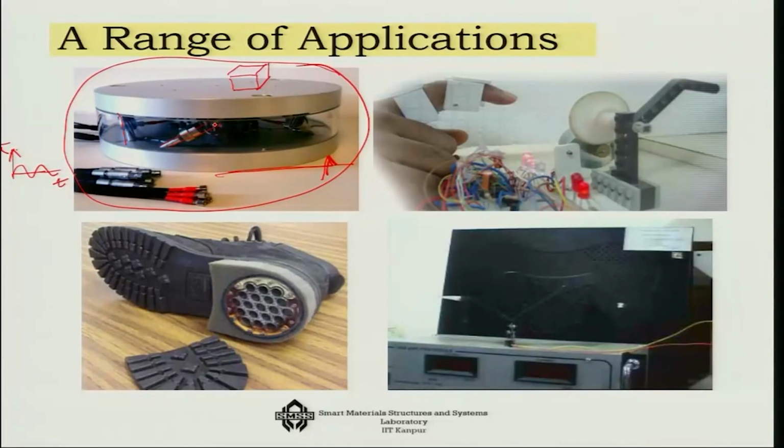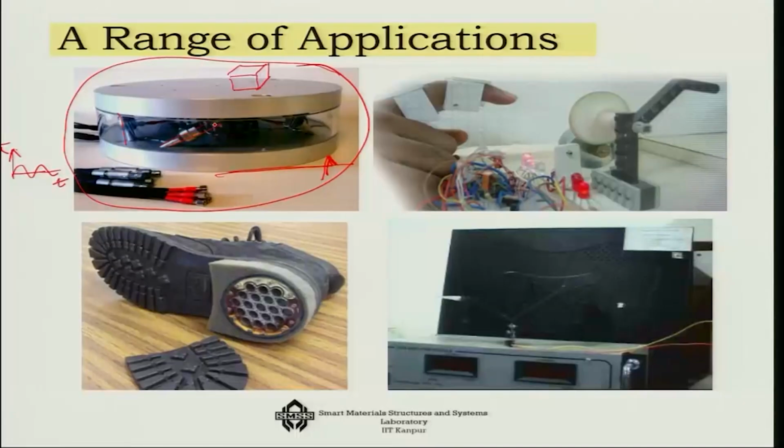That means the system is not going to resonate, and if it does not resonate, it will absorb this vibration within itself. So how do I do it? Because this base excitation can keep on varying, one way is to use a piezoelectric material which can change its size. You can increase or decrease the leg length as and when required, and through that you can stop the excitation from passing through.